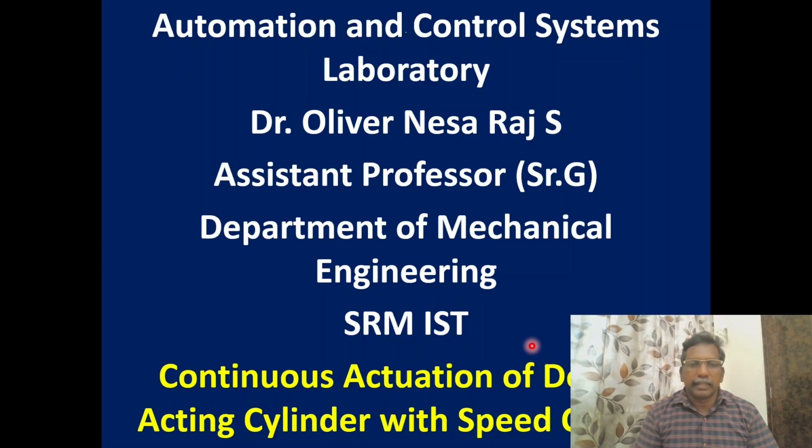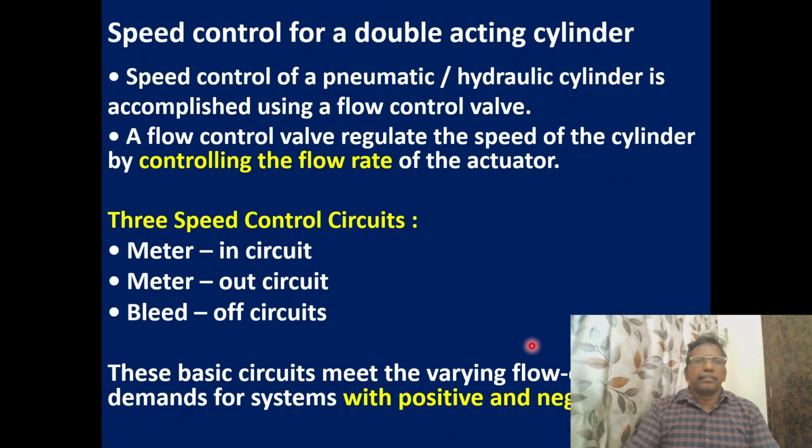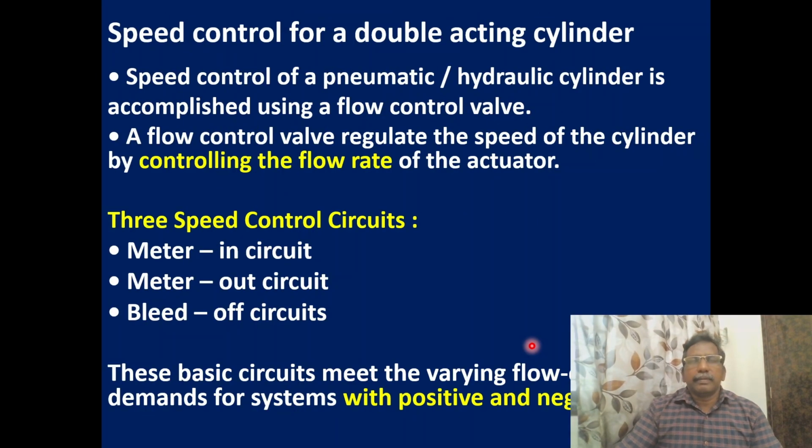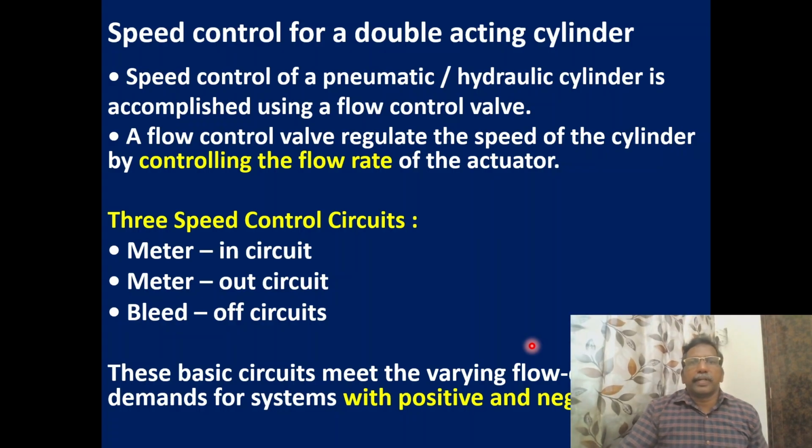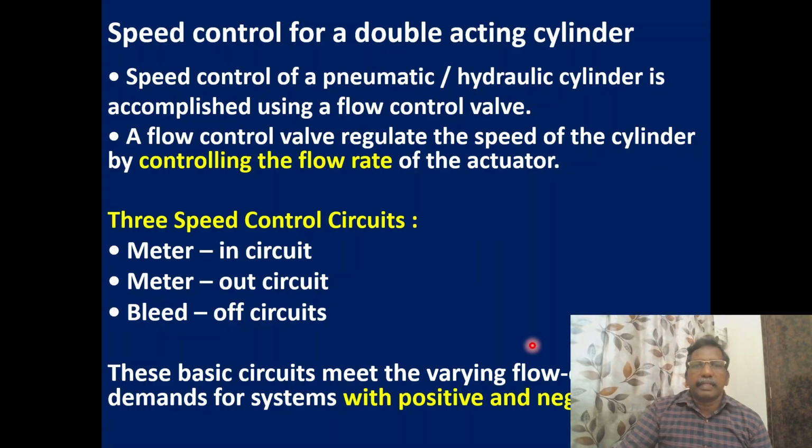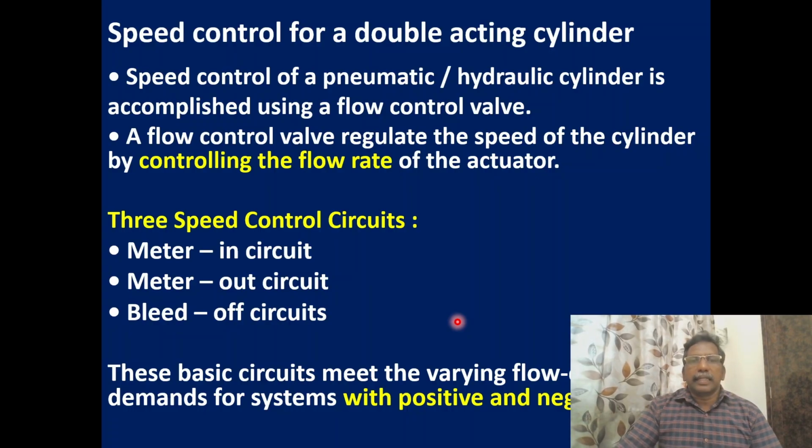Today we are going to continue with a new concept, the continuous actuation of a double acting cylinder with speed control. So what is meant by speed control? Speed control for a double acting cylinder. So why do we need speed control? Speed control of a pneumatic or hydraulic cylinder is accomplished using a flow control valve. A flow control valve regulates the speed of the cylinder by controlling the flow rate of the